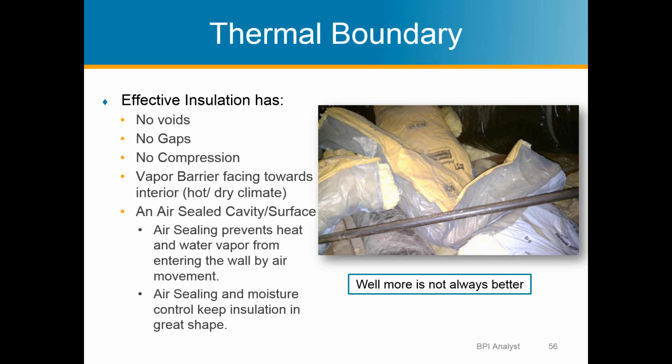And of course, penetrations like electrical penetrations that go from cavity to cavity down the wall, sealing those is also a good idea. Again, you just want to minimize the amount of movement that air can have in your wall. But California code requires at least that the top and bottom of the walls are air sealed at the attic. So at least if you can get top and bottom, it helps.